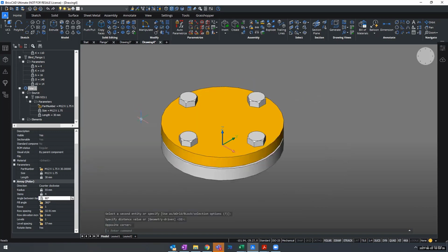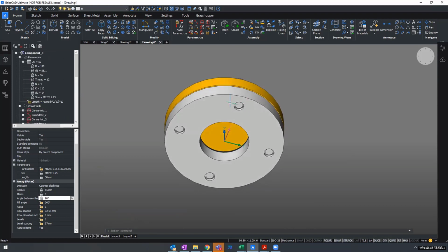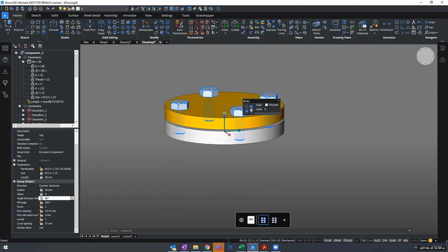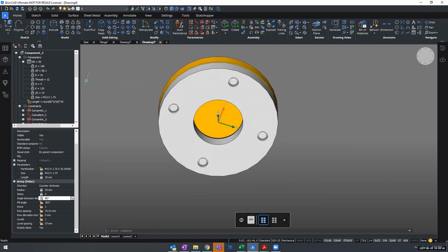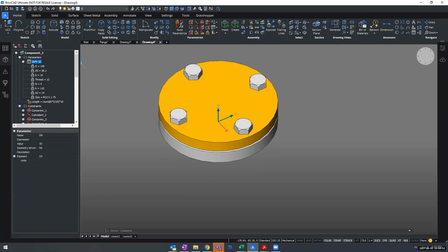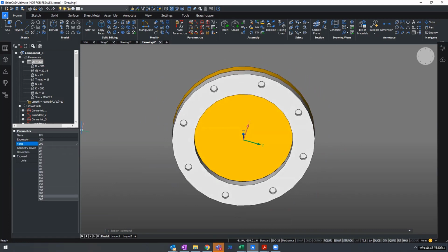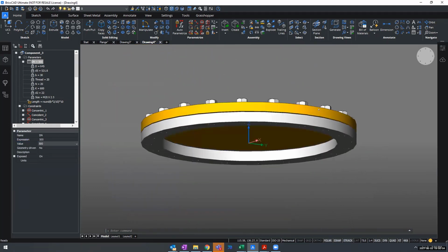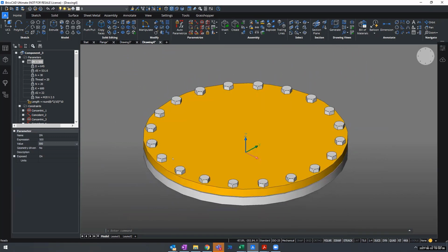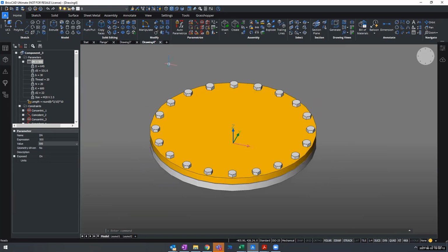So now everything should work properly. The entire model should be coordinated. So if I make a change to one of the global parameters here, not only the number of holes, for instance, will change, but also the number of bolts. So I can check that by changing, let's say, the value of this design table here to something else. And that seems to work fine. So now we have a full assembly with 3 sub-assemblies and some bolts. And again, I can create a new component from that to use further in a larger assembly.